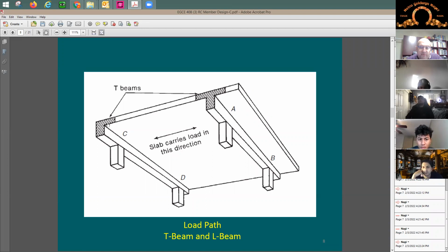When it comes to analysis of reinforced concrete sections, in the analysis part, we have either a rectangular section or a T section. So you see here, I have your rectangular section, and the T section. When we come to analysis, these T sections include T and L. The same principles and the same analysis that we do for T sections is going to be exactly the same thing that we do for L sections. But when you go through the code, they just call it here T section. Whether you have the flange on one side or two sides, it doesn't matter.